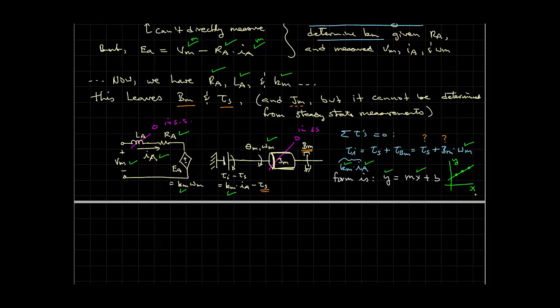Or we get to change the current that we apply to the motor. So you could actually power the motor with a current controlled power supply, and thereby you'd set Ia directly, which would be indirectly, effectively setting tau I. And you can try that. But there are some practical limitations or implications of what is more readily achievable in the lab.